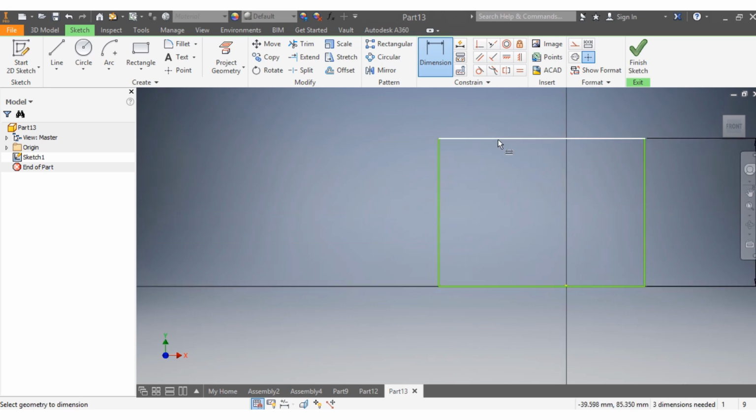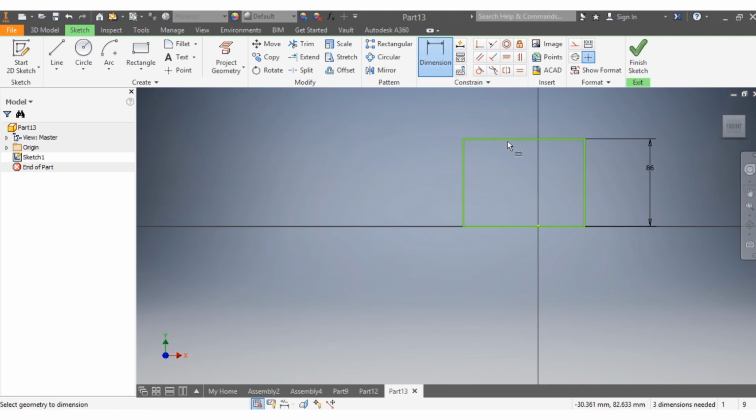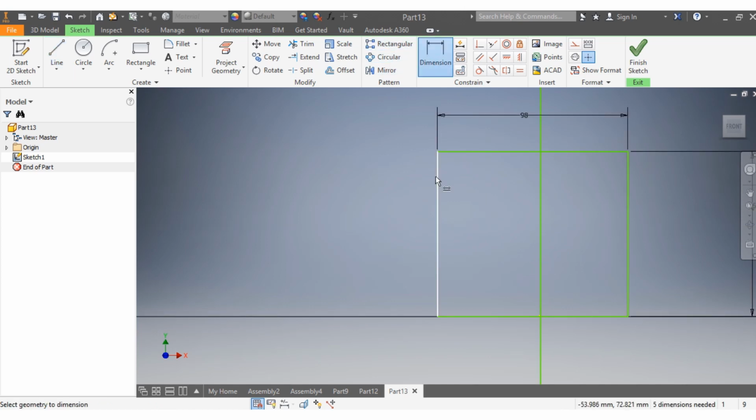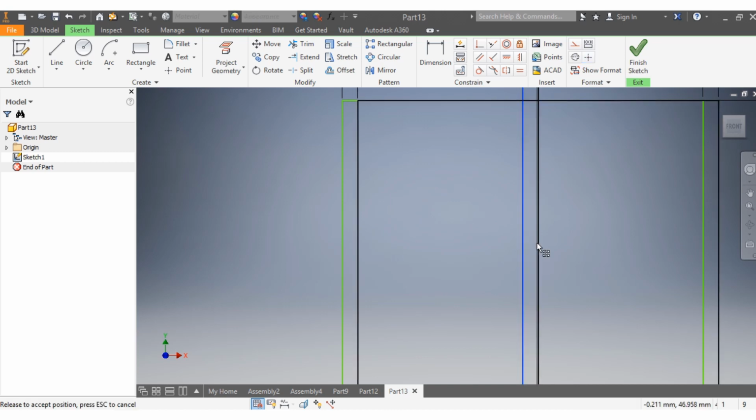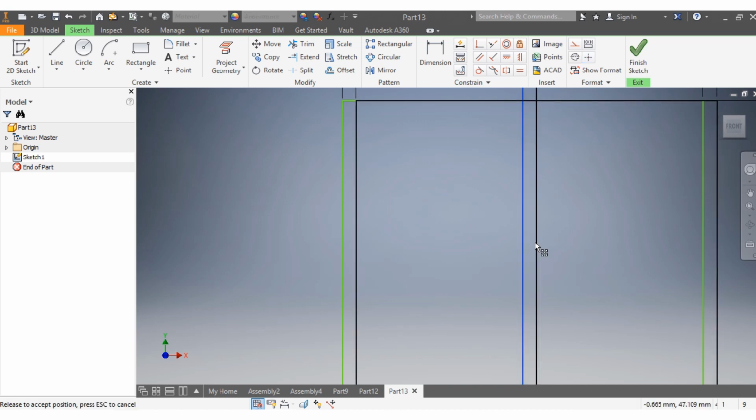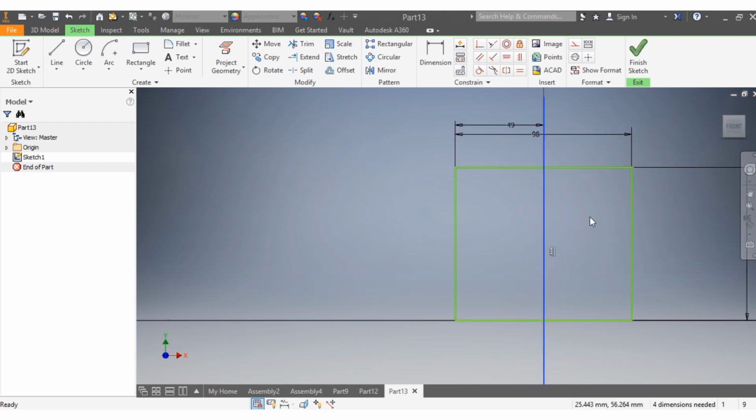The next thing that I want is the size, or the diameter, of my piston. Let's say 98 millimeters. Great, 98 millimeters. So I can now draw this line here, which is for guidance. That one needs to be at the center of my drawing, so that needs to be 49 millimeters. I'm going to put that line back there, right? So we go saving this together.